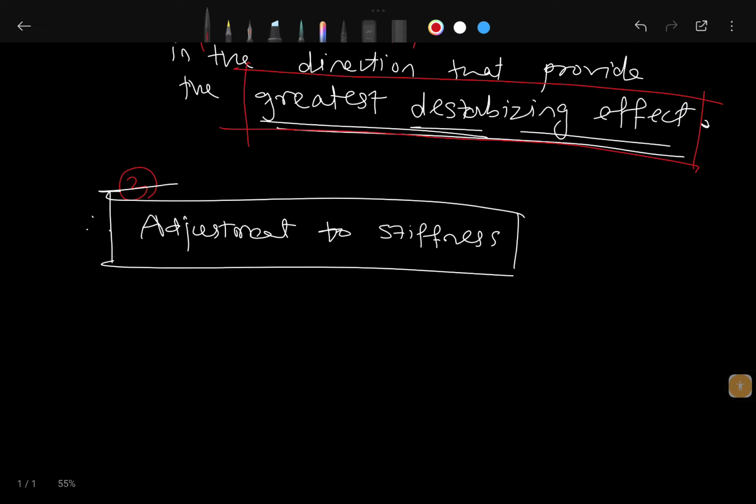Now for this, the analysis of the structure to determine the required strength of components shall use reduced stiffness. A factor of 0.8 shall be applied to all stiffness that is considered to contribute to the stability of the structure. What factor have we used to modify the stiffness? 0.8.